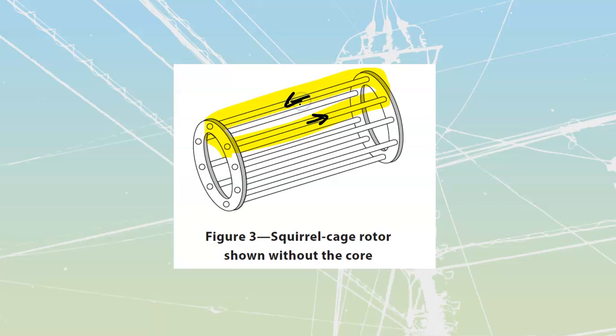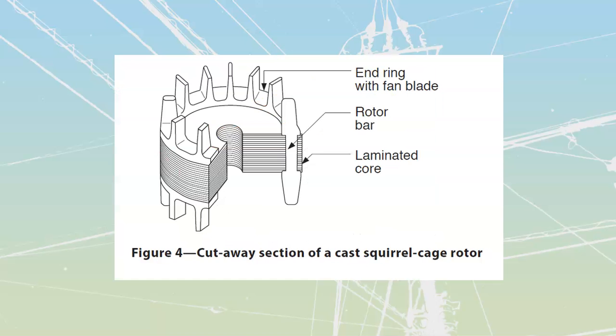These bars are not here for mechanical support. These bars are here for conducting current, and large amounts of current. Same with these ones over here. We're going to have current travel through these bars, through the shorting ring, go down through the next one, and then loop back around. Large amounts of current flowing through low amounts of turns. This is going to be my transformer secondary.